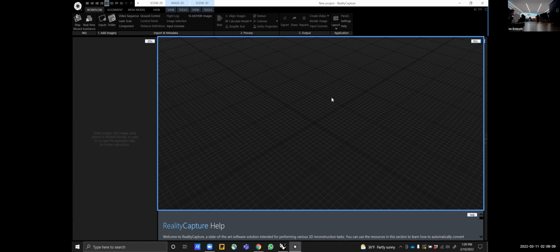There are two ways you can do photogrammetric capture. One is just taking a series of photos of an object. I can demonstrate with Adam's water bottle, if that's okay. Basically just go in a circle around the object at an equidistant radius from the center of it, with one or two passes closer and farther away. You can do that as a bunch of photos or as a video and then import it into the photogrammetry software. You can pull stills from it. I'm going to go through both of those methods now.